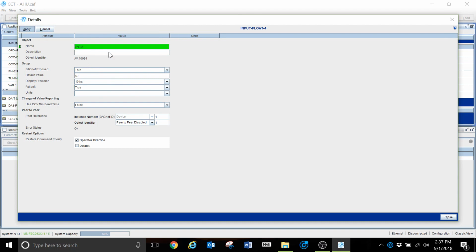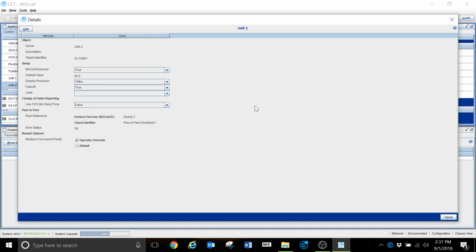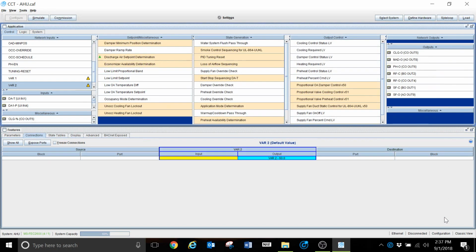These two numbers are going to be very important in calculating the rate of your discharge air temperature set point changes. At 60 degrees or above, that span block is going to be at the minimum 55 degree discharge. Below 40, we're going to be at the maximum of 85, and in between it's going to float.